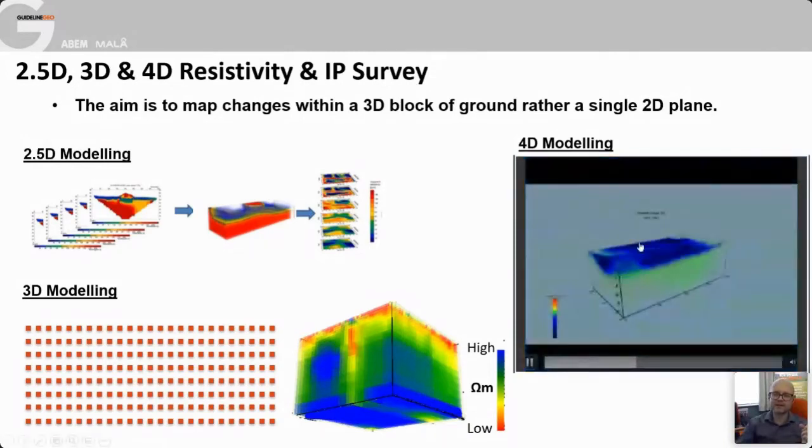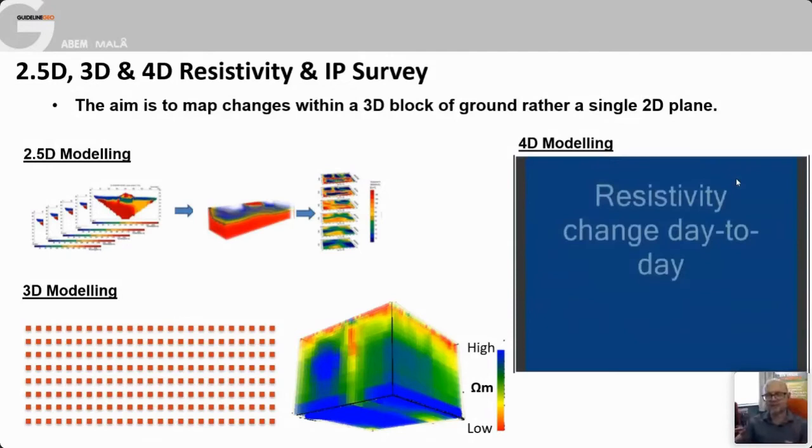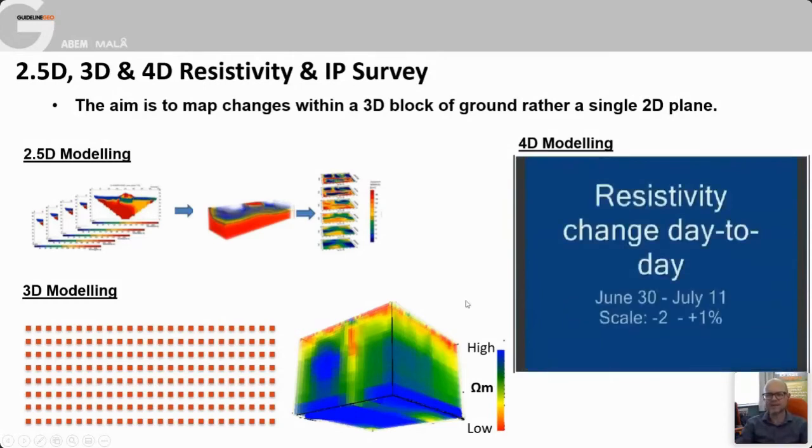So you see the rainwater lands, reduces the resistivity near surface, but then as the water percolates through, it causes reactions within the waste in the landfill site, and those reactions are causing gas to be generated, and that gas is then increasing the resistivity near the center of the pit. So we start with the low, then the reactions begin, and we start to see the resistivity increase again. So that might be something that is required.